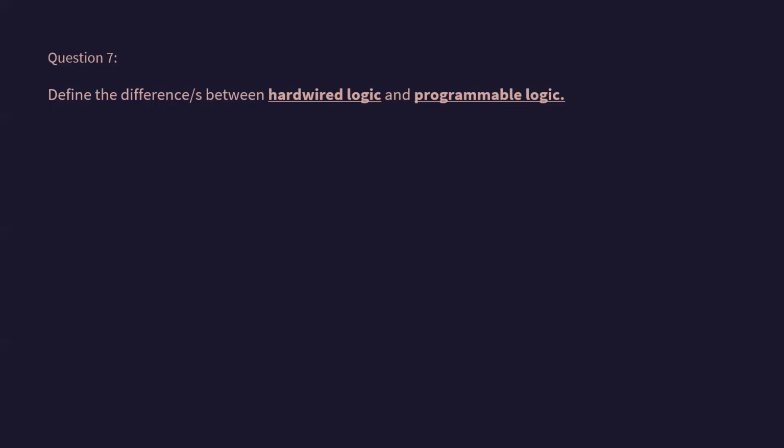So there would be wiring an AND gate, maybe with another OR gate, and maybe with another inverter, which is a NOT gate. I don't think I have shown you that one. An inverter has just one input and one output. When you put logic 0 on the input, you get logic 1 on the output. And the other way, if you put logic 1 on the input, you get logic 0 on the output.